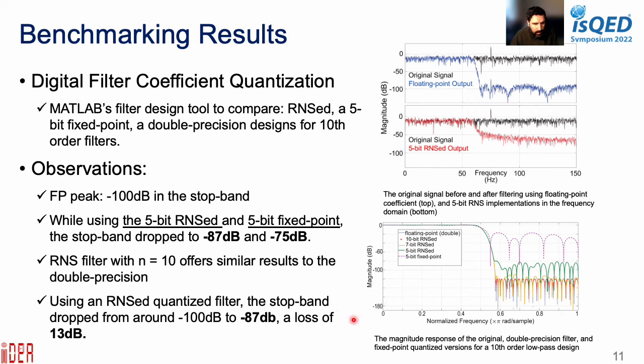And finally, to verify the proper operation of the RNS FIR filter, we stream some data to analyze the input-output response using an RNS representation with a similar bit width, 5-bit. RNS filter presents an acceptable input-output response similar to 16-bit fixed point coefficient quantization.